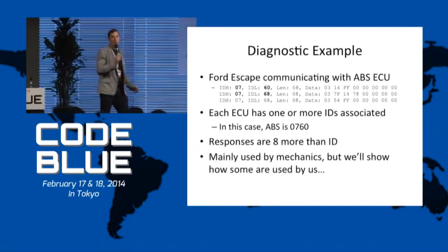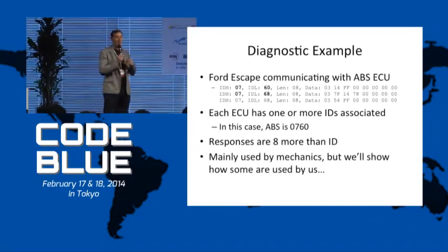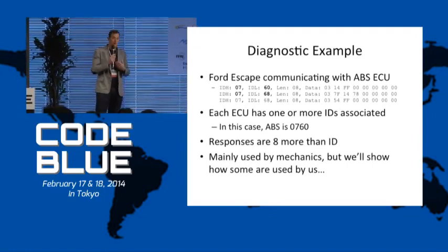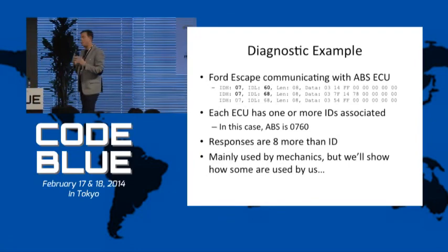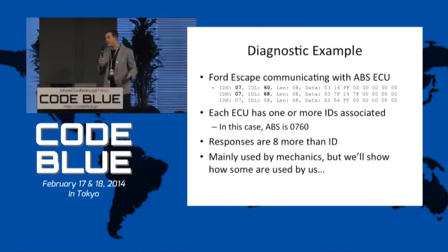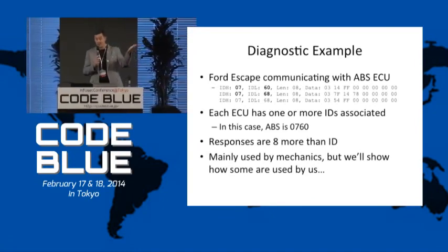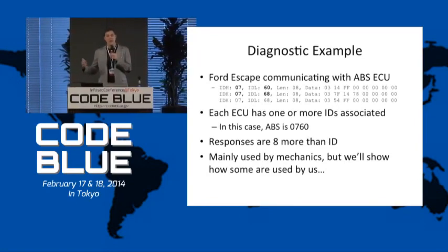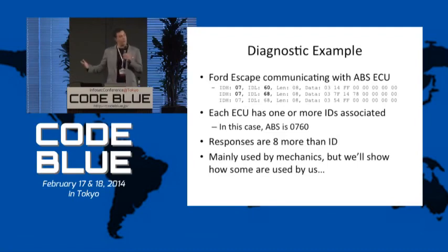This is just a way for mechanics to diagnose certain computers in the car. For example, they might say, hey, engine ECU, can you tell me the status of your oxygen sensors for emissions testing? And it will give it data back. You normally don't see these when you're driving the car. The reason they're diagnostic messages is they're used for doing diagnostics when the car is, say, up on jacks, right? Again, while they are mainly used by mechanics for mechanical work, we'll show you how we leverage them to be used while we were driving the car as well.